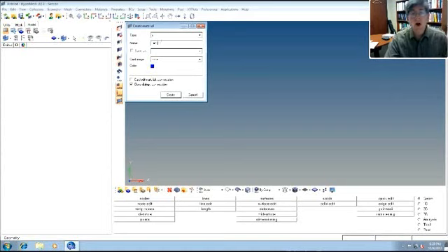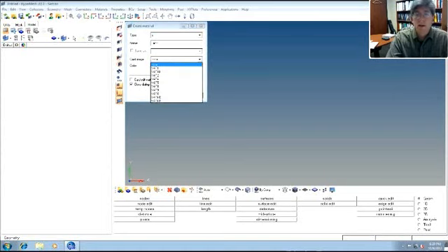And the important thing is the card image. So you can see now we're talking about Nastran. It supports MAT 1, MAT 10, MAT 2. We're going to use MAT 1. All right? So we're going to define a MAT 1. We're going to call it birch. And then if you click this one, this allows you to edit the card directly.